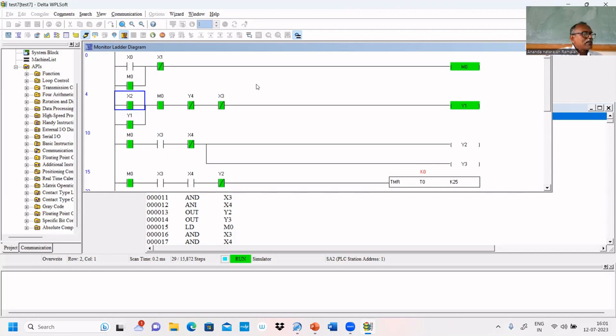After some time, what will happen to the lower proximity, the bottom proximity switch? It becomes 0, because the level will rise above that proximity switch. That's why it is not empty. Am I correct or not? That way we have to simulate. Still, the inlet valve is on. Once the level is reached, what will happen to X3? X3 becomes 1. The tank is full, X3 becomes 1.